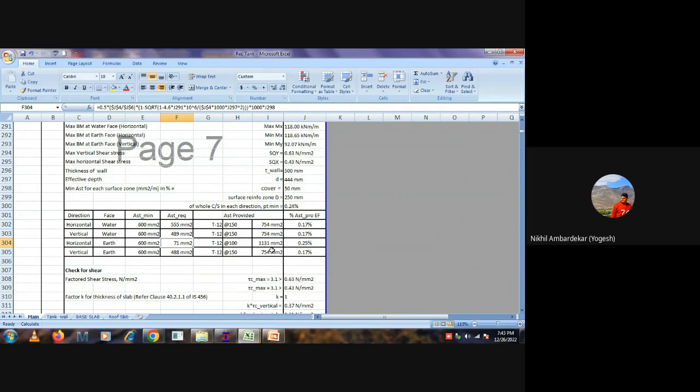Okay, so now again we will try to reduce it a little bit, because we need only 600 reinforcement as against the 1131 we have provided. So maybe we can increase the spacing. Good. Can we increase further? Let's say no. So just stick with 150. Here also it looks fine. Everything is fine. Someone who wants to go with 10 can try it. Let's see what happened. It's failing. So you can also adjust the spacing. Instead of 150, you can go with 100 and check whether it is fine. So it's up to you.